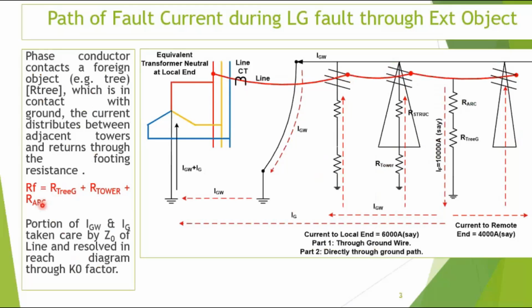Arc resistance is not that much. Generally, something around 10 ohm maximum. It should not go beyond it. Very rarely do you find that.